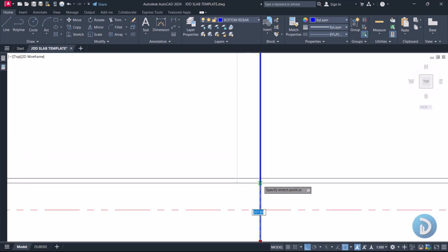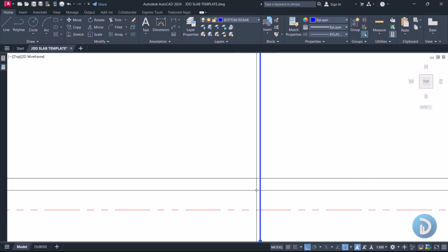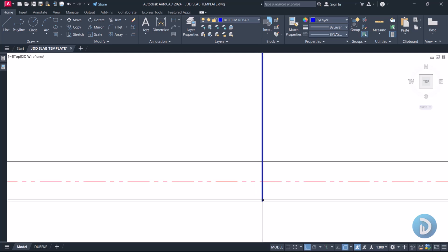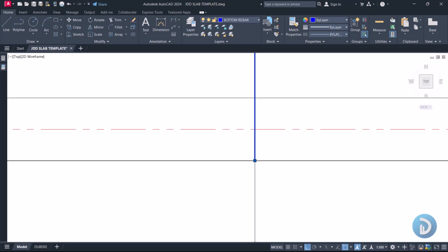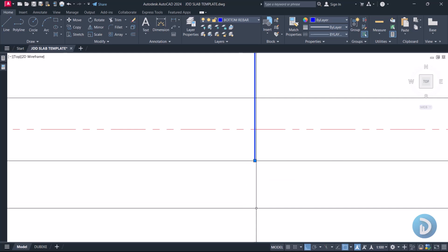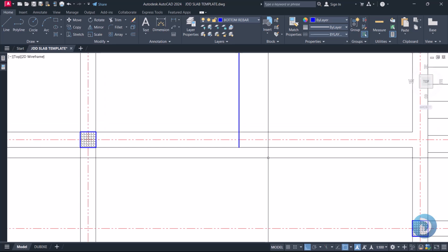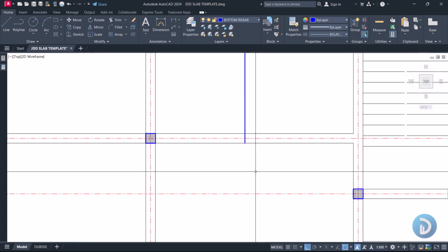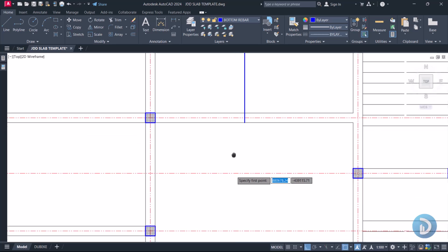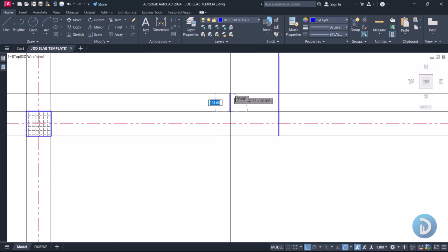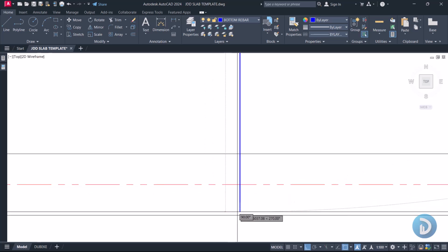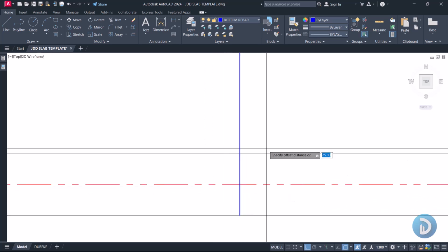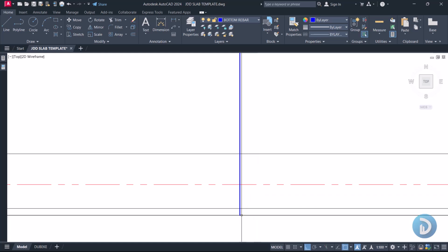Okay, you can choose to retract out of this beam while they are stepping on it if it is not properly bonded. So it is always advisable during construction, you can extend this to about a minimum of 150 millimeter, but we'll leave this detailing at the end of this beam. Okay, regarding our detailing per panels, we'll start a new reinforcement that will run from this point up to this point, and do not forget our concrete cover of 25 millimeter.